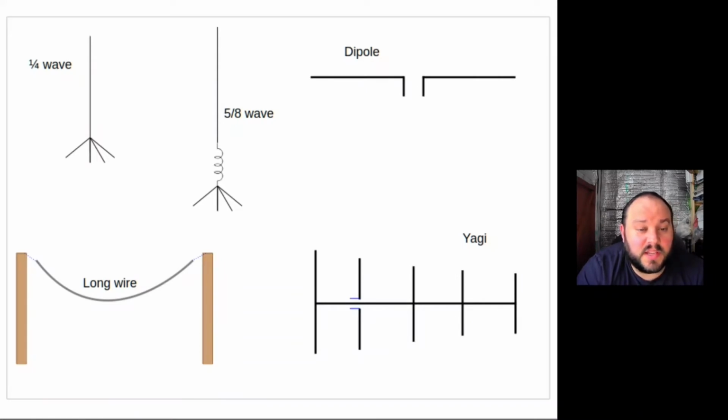The next aerial you see here is the dipole. This can be situated either vertically or horizontally. Typically for UHF and VHF it is vertically polarised like the quarter wave and 5/8 wave, but can also be used effectively for much lower frequencies like the HF band, where it can be fixed horizontally due to the much greater length required for HF frequencies. The dipole is versatile and effective and can be installed across a garden, on a roof, but not really in a vehicle.